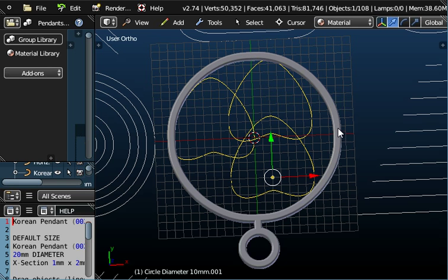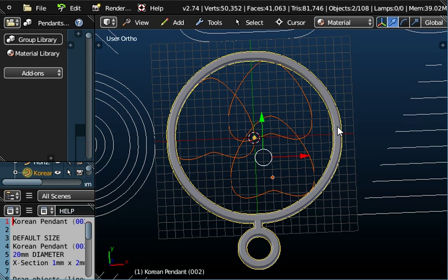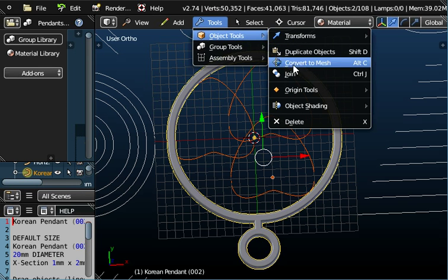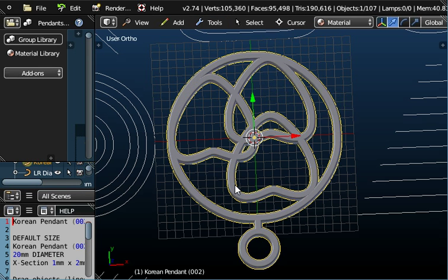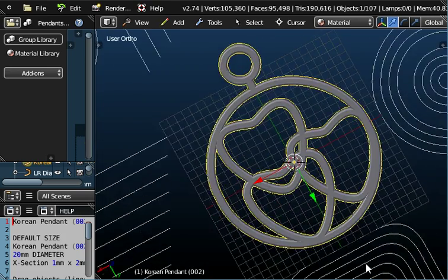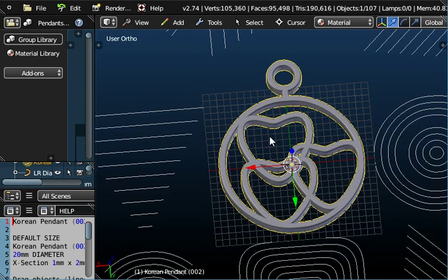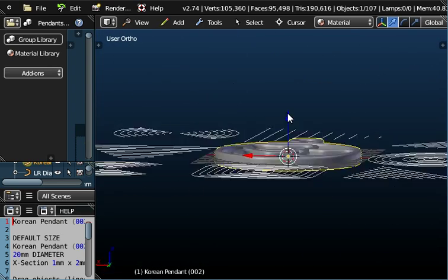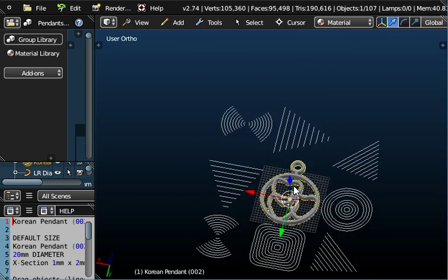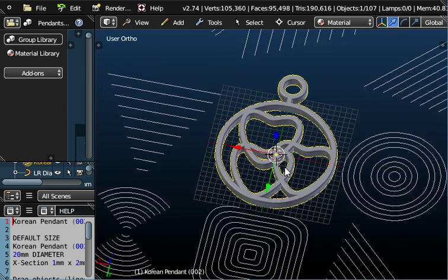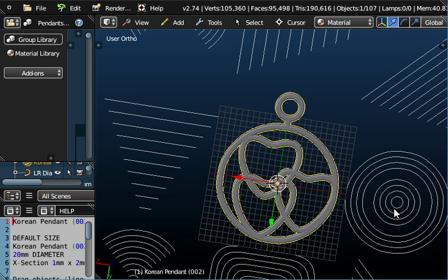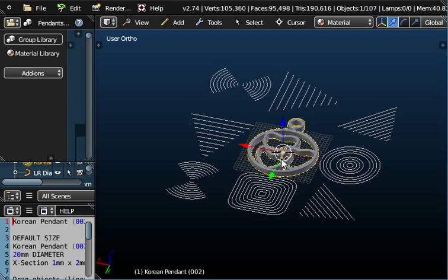And then if I just join them to the pendant itself, so I'm just holding down the Shift key and highlighting the pendant itself, and if I join them with the pendant itself, now I've got a solid object made up of those 3 heart shapes in the center of my pendant, and this object can now be printed. So you can see how powerful this is. I've very quickly and easily added objects to the center of my pendant here, and created a new pendant.